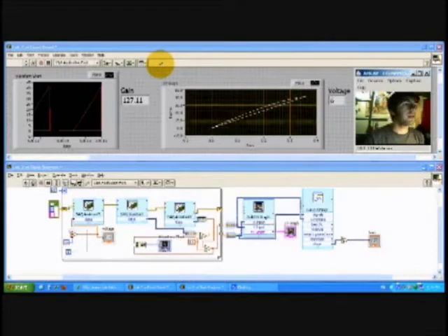So, as you can see, the overall program looks pretty much the same. I haven't even renamed it from lab number 2. Really, the only difference is that instead of running between -5 volts and +5 volts, we're running between 0 volts and 6 volts. To only read the current, we have to divide by the resistance, and so we did that here. The resistance is actually 1K, but to get our numbers more easily visible, we divided by 0.1, so the graph is easier to see. But then when we were making the graph, it's pretty much exactly the same once again.